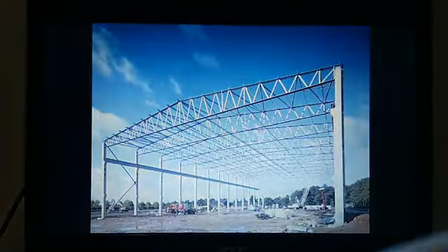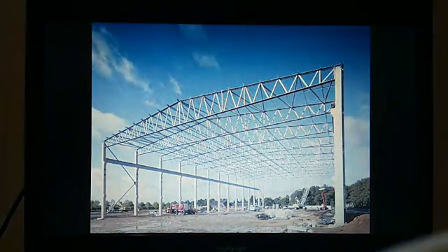So why? Because your truss is with some pitch, with some slope, right? So by that it is called a pitched roof truss. Again you can see here a trapezoidal roof truss in a real application. See how your top chord is supported with the help of plenty of bracings like this. So these are all bracings, right? That's why it is called a braced roof system. So this is the trapezoidal roof truss.